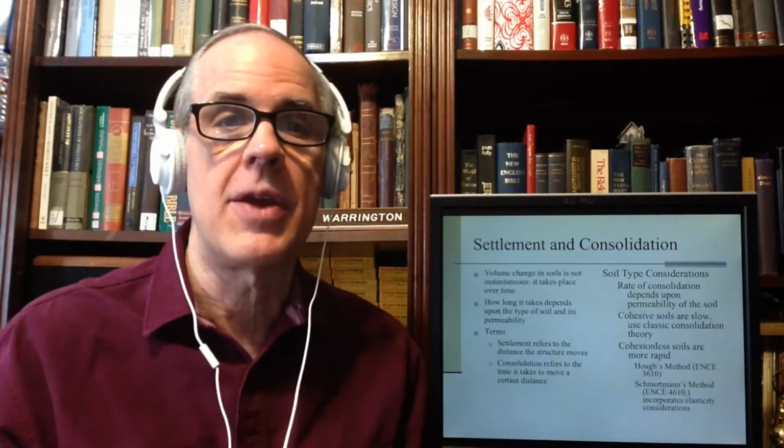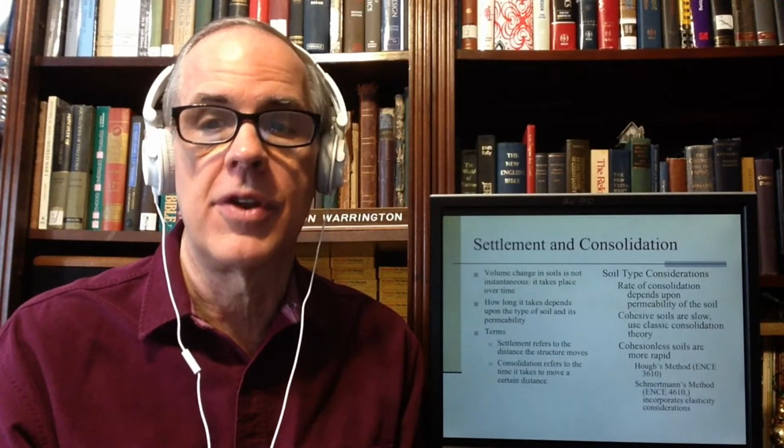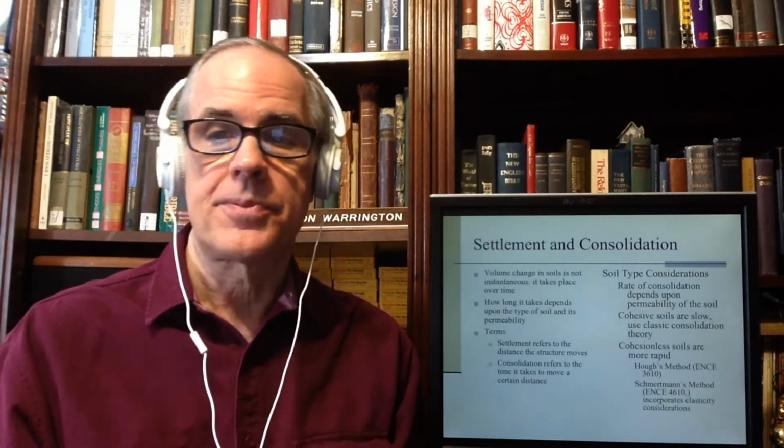Settlement refers to how far does it go? What distance does the structure move? What distance does the soil compact under it? Consolidation has to answer the question, how long does it take to get from point A to the point B we figured out in settlement? And those are the two questions that we attempt to answer with settlement and consolidation theory. The rate is, again, how long it takes, depending on permeability. I kind of repeat myself in this slide, but repetition is the essence of education. It depends upon the permeability.